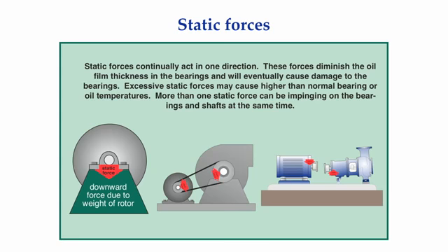These are three very common sources for loads on bearings. Also be aware that static forces are continually present, whether the machine is running or not. It is important for you to remember that dynamic and static forces can and do exist at the same time.